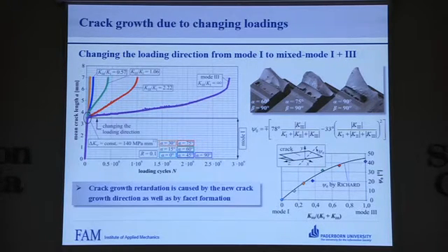The crack growth retardation effects here are also caused by the new crack growth direction, whereby the crack twists out of its previous orientation and at the same time separates into multiple daughter cracks, so-called facets, which also have an influence on the crack growth rate. The measured crack twisting angles also coincide very well with the hypothesis by Richard.